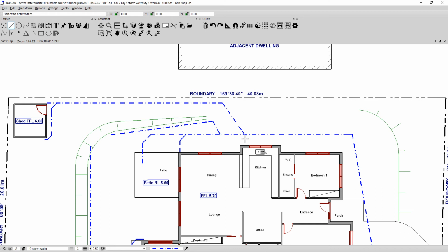Okay, how do we put in the arc that wraps around here? There are several ways, so let's go up to our menu. You may recall, if you looked at these menus earlier, that this is where you find circles, arcs and ellipses. So click on the parent part of the menu at the top, and look for something similar to what you're after. I've got arcs here. Now this one looks like it would probably do the job, and it will. I could also use a circle and then trim the circle to become an arc, so I could trim a piece out of the circle. But let's try the arc tool first.